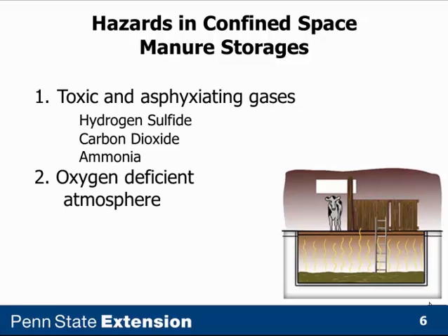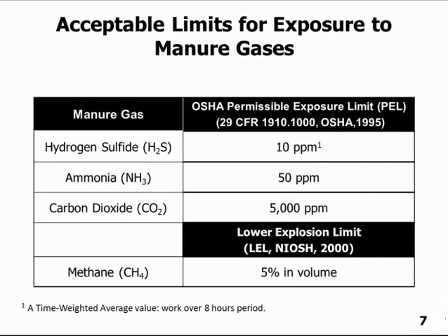It also has the possibility of having oxygen deficient atmospheres. In some confined space manure pits, the oxygen content can be near zero. And of course, we could also have explosive gases in these manure pits. Most important of those gases would be methane.